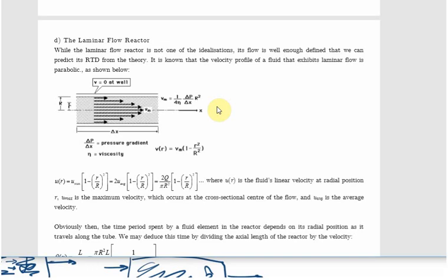And the way that we find the RTD from this more complex situation is, first of all, we start defining the velocity in terms of the age. So once more, we start with the laminar flow definition, right? So laminar flow, we know that this is the laminar flow velocity distribution. So the distance from the center here, and then the maximum velocity, the center line velocity is there, where the center line velocity is twice the mean velocity. So there exists some mean velocity here, somewhere like that.